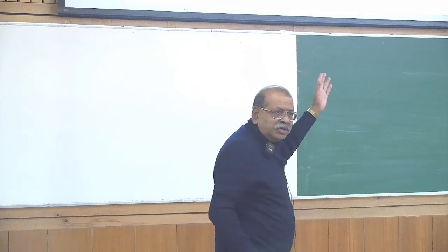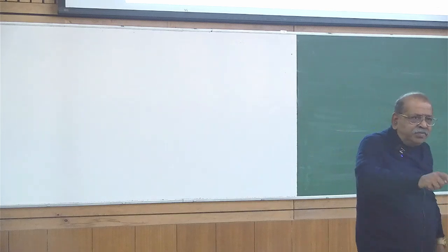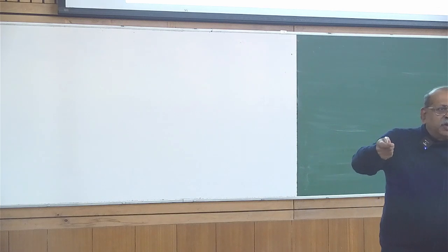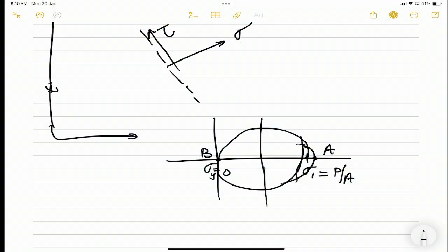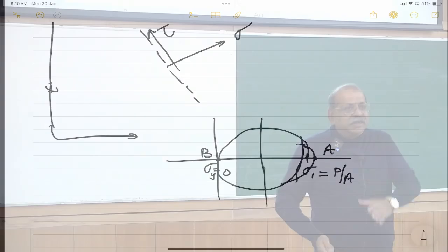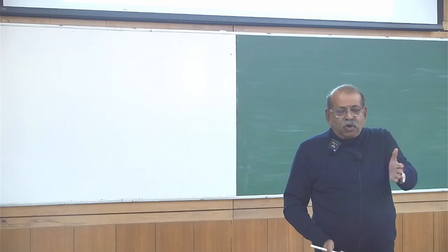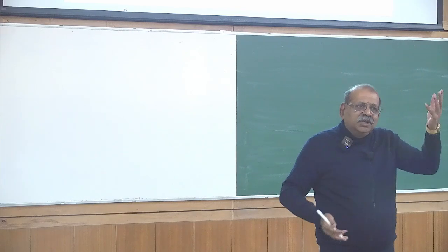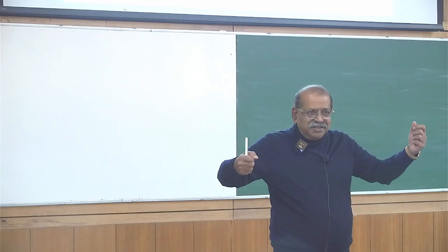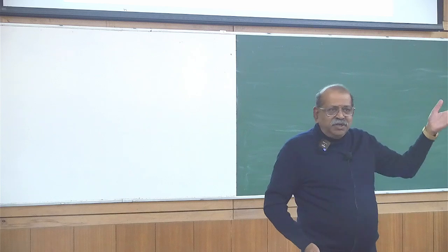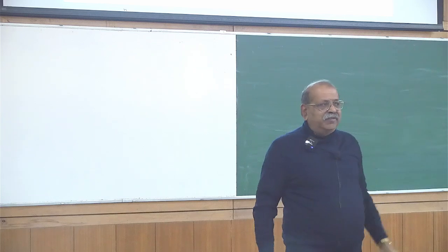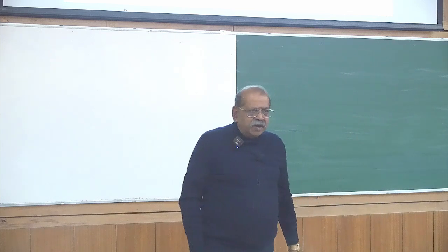You will be able to see that, and that is why I taught Mohr circle before, because even for this loading there is a shear stress. It is not that shear stress is not there, but it is on another plane. What we are finding using all these analyses are only tensile stresses, but a shear stress corresponds, and that comes at an angle of 45 degrees. Okay?